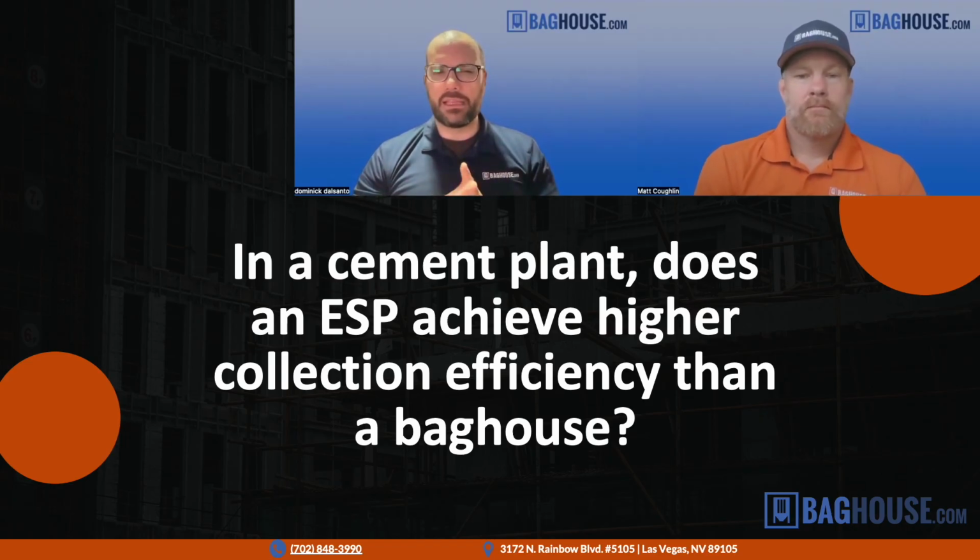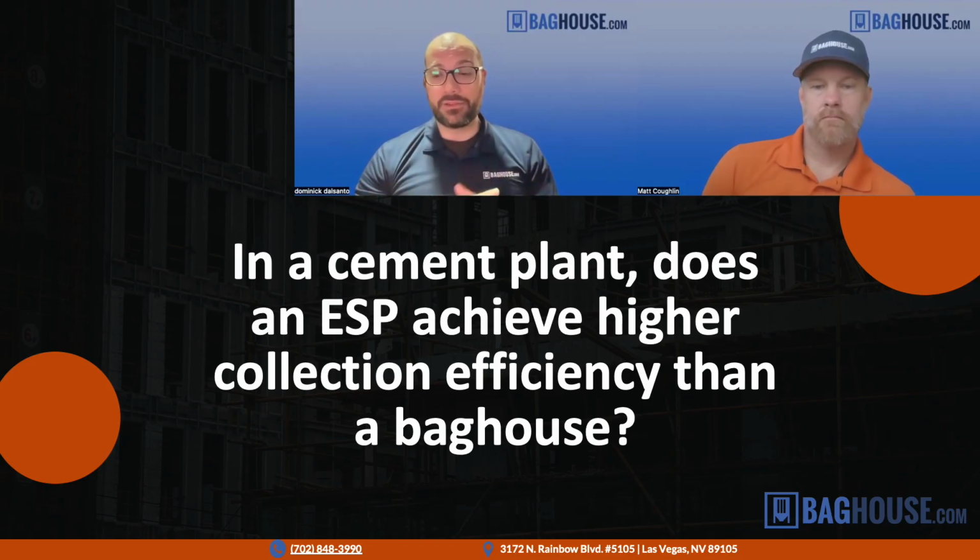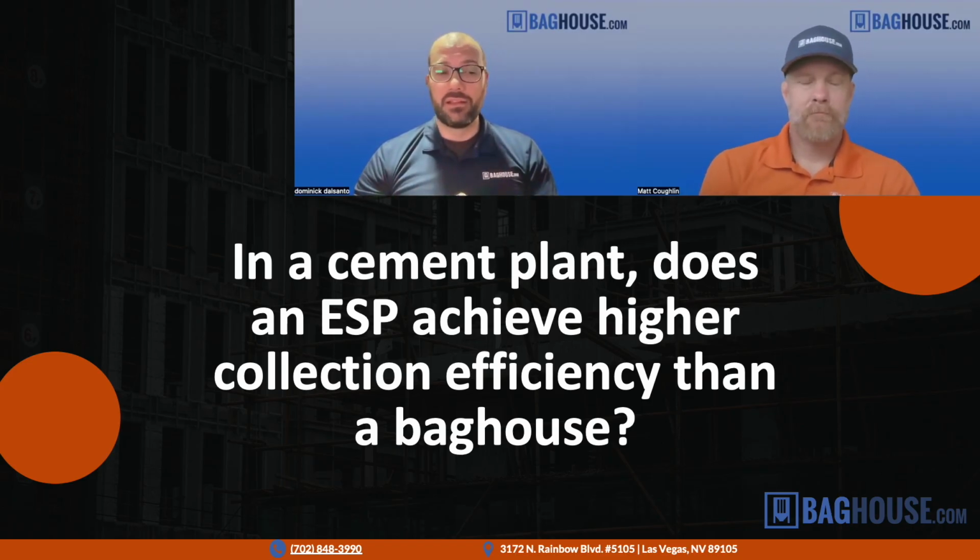Some smaller applications use wet ESPs where they use water inside of it. Those are comparable to baghouses in a lot of cases, but for a lot of other reasons, they don't usually end up in cement, water and cement dust obviously not mixing very well. But normal ESPs versus baghouses are almost always less efficient, and baghouses are required basically according to the most current regulations.